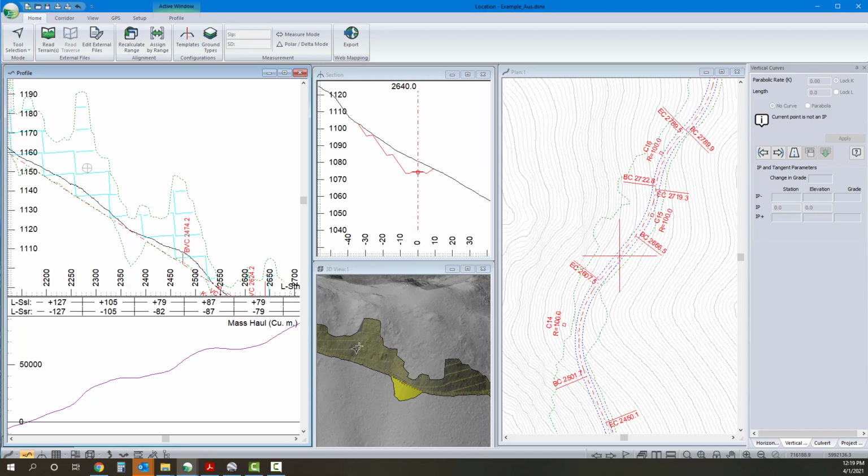This gradient has our benches running back towards the ditch. So ideally, our surface runoff gets intercepted by the benches, which are essentially acting as ditches in this case. The water moves back towards the ditch line and you can dispose of it appropriately, or at least armor the ditches appropriately to prevent erosion. And that is another example of working with the Benches 18 template component in RoadEng.